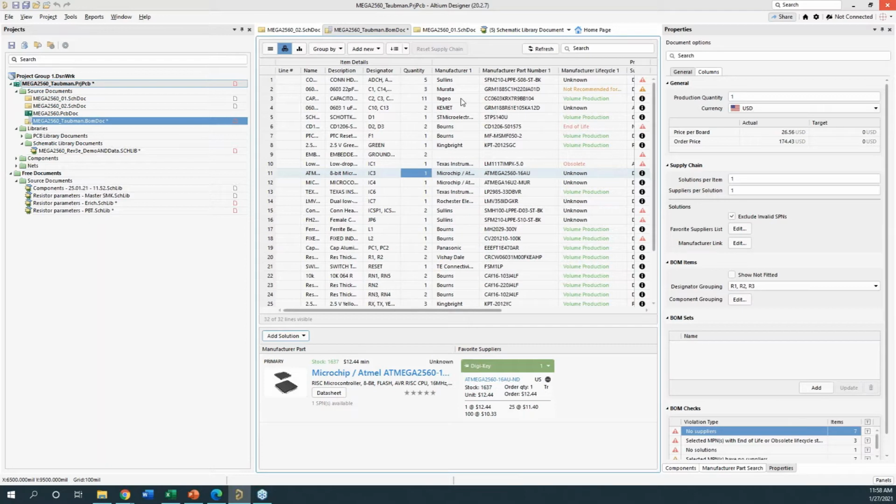In fact, Active BOM leans very heavily on part choices. If you don't have part choices, I wouldn't even bother with it. I would just go with the classic method of doing the bill of materials and reporting. That's probably what he was saying: as long as you have a part choice and you use the Active BOM, this stuff will fill itself in.